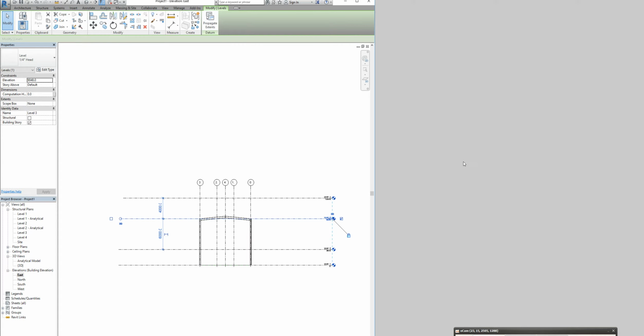See how, so what happens, so see how all the members, the structural members, the columns, they actually stretch to accommodate the change. So that's what we want to show the students, that in a structural module, you got a lot of flexibility when you need to do change in design, which happens quite often in a project environment. You are able to just change the shape of the building by modifying the grids, which is quite useful.